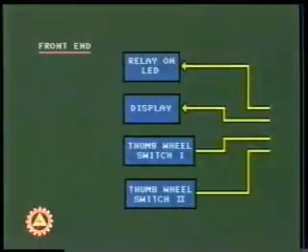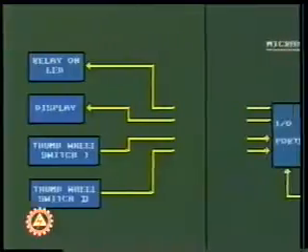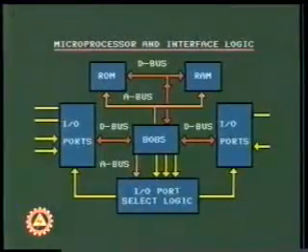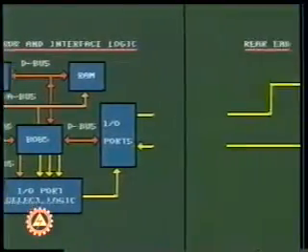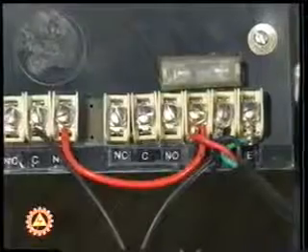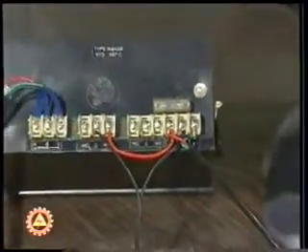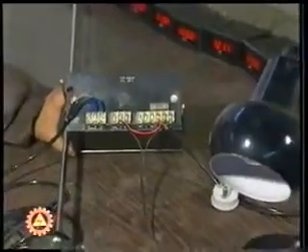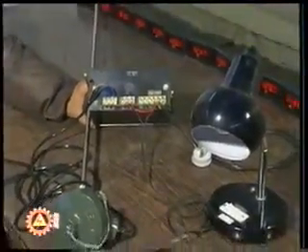In the example system we have been dealing with, this corresponds to having the circuit blocks arranged in this way. The number of signals from any given circuit block is kept as minimum as possible. The thermocouple output sensitivity is of the order of 50 microvolts per degree centigrade. This voltage is too small to be processed. We need to insert some gain stages before the signal is fed to the AD converter.